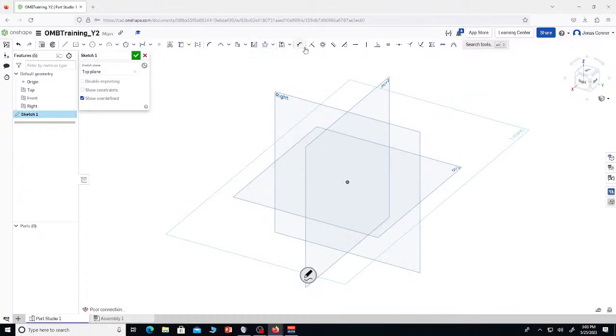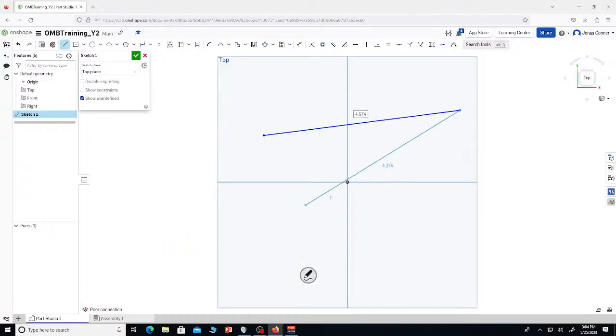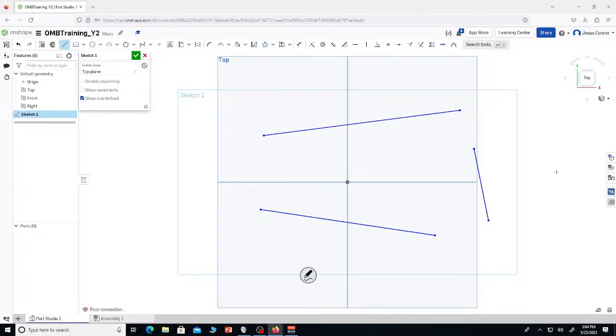Let's see, anything else to hit? Definitions. So if I've got a bunch of lines, right? Separate lines. These right here are your definitions. So I can say tangent if I've got a circle right here. I want this to be tangent to that. Now it'll be perfectly on the edge. Anytime I move it, it'll be tangent. That's useful for pulleys, gears, things like that.